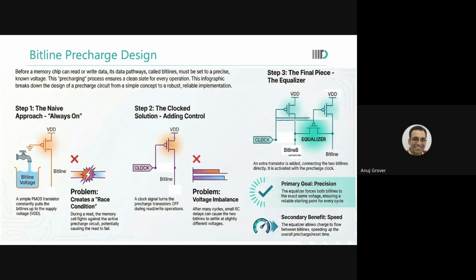No, we said that an equalizer would bring them almost to the same value. That almost, we have to discharge the bit line extra. So even though I recovered a few tens or hundreds of picoseconds by bringing the reset a little earlier, now I have to discharge my bit line 2 millivolts, 3 millivolts, or 5 millivolts extra to be able to do a correct read.